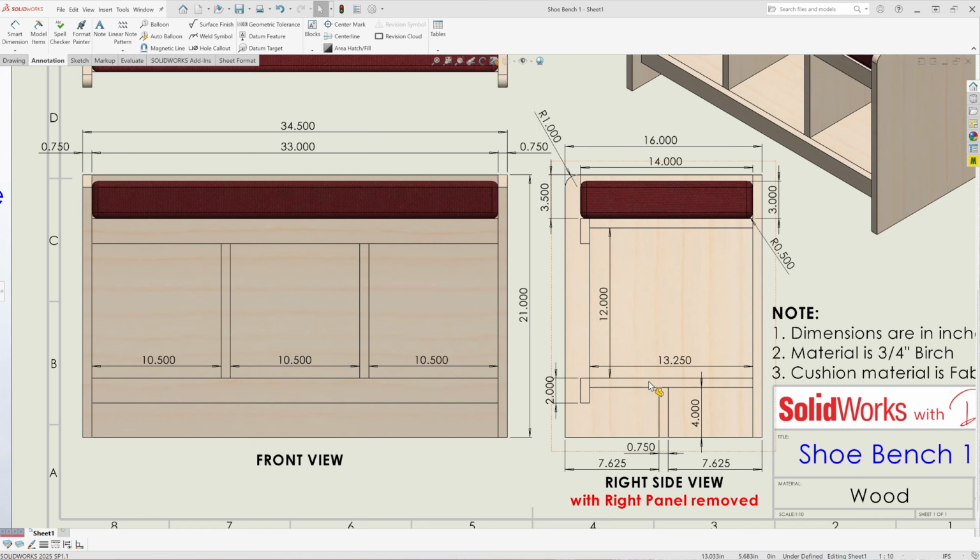Then the bottom panel is 13.25 inches wide by 33 inches long, and the top panel is the same. So it's not dimensioned, but it's the same as the bottom panel. And then in front of the bottom panel, there's a 2-inch lip, and that's 33 inches long as well, and it's the same for the top lip. Okay, so moving up to the top, there's a 1-inch radius at the top left corner of the left panel, and the right panel.